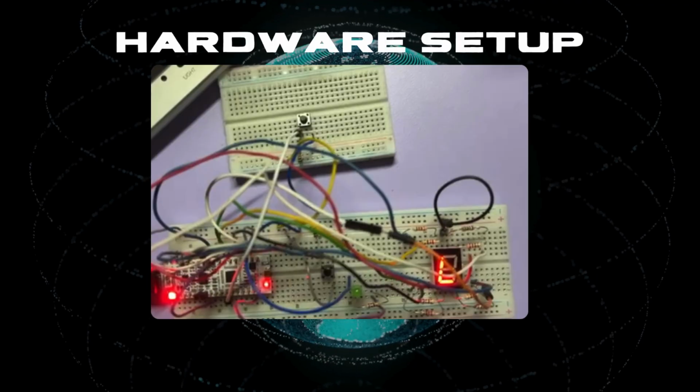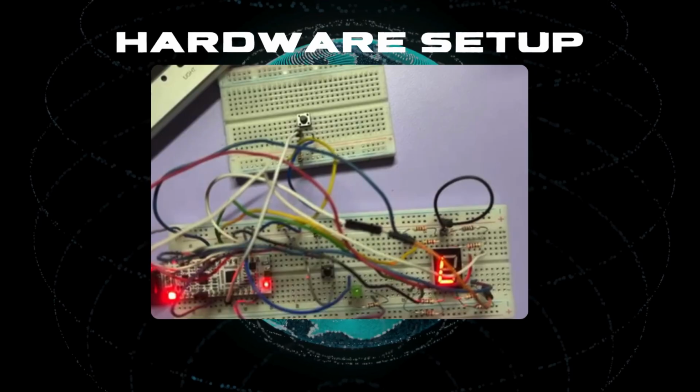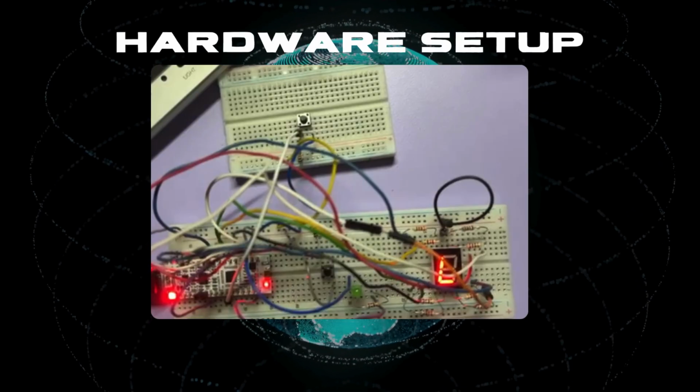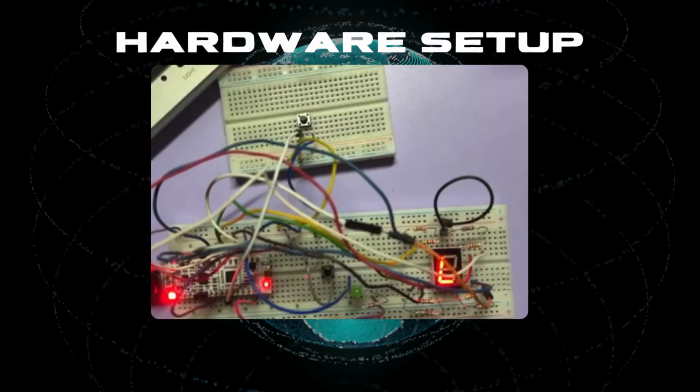Next, we use 2 types of resistor. The left side is a 10 kilo ohm and the right side is a 220 ohm. Lastly, we use a green LED, which turns on when the number of vehicles in the car park is less than 10, as our output. And we set it as active low.